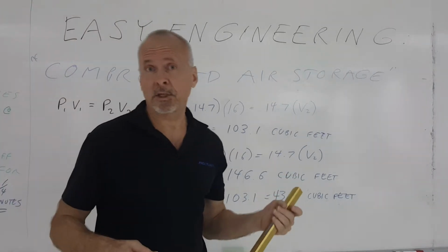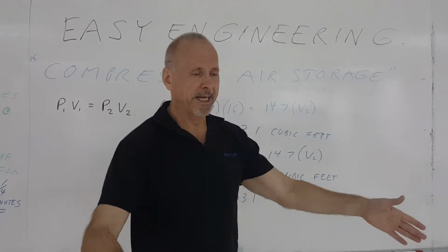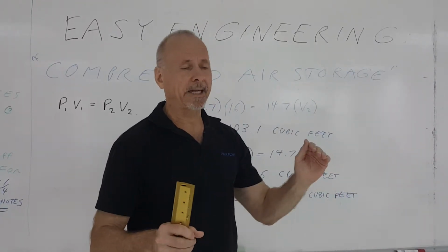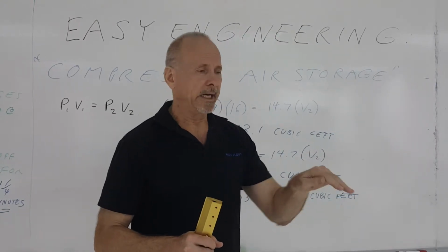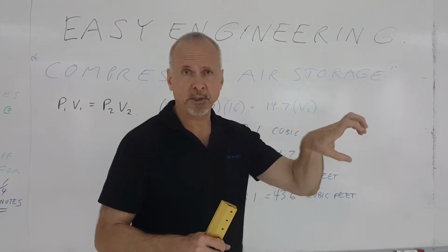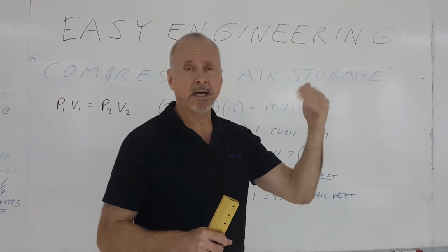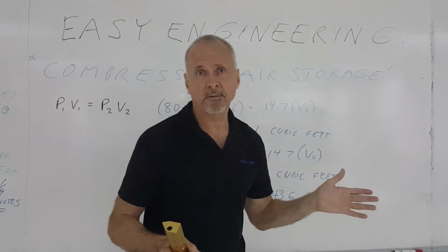It's stored under pressure. Normally how it works is you get a, say, 120-gallon tank, and the pressure is set so that the compressor fills that tank, and it turns on when the pressure falls below a certain level, say 80 pounds pressure, and then it continues to fill that tank up until it hits a higher pressure, say 120 pounds, and then the compressor turns off.